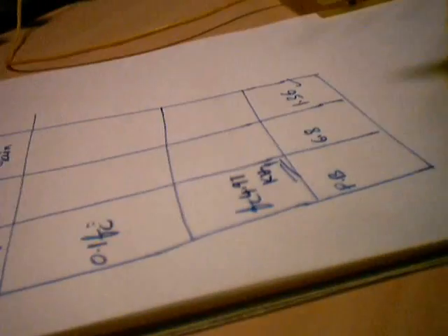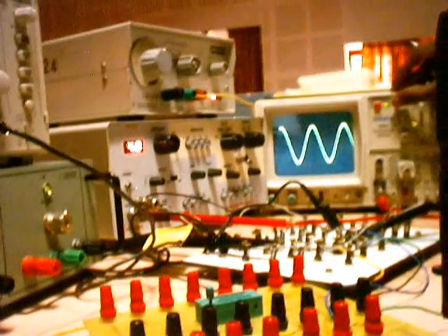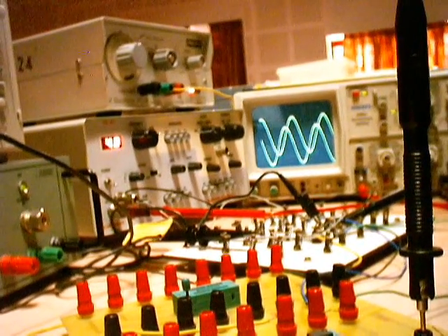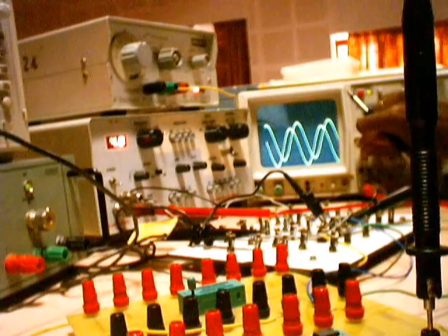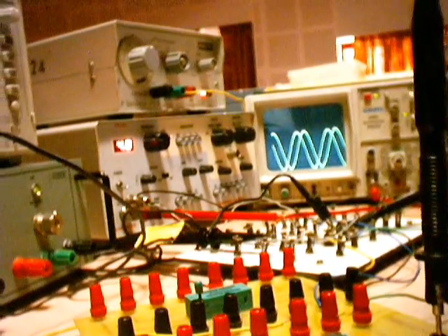So this frequency is now equal to 4.97 kilohertz. Now FC is 4.97 kilohertz. Of course, you can find the output voltage here. Output voltage happens to be, this is in the 1 volt range. Before we measure the output voltage, ensure that your input is at 5 volt. It is there at 5 volt.